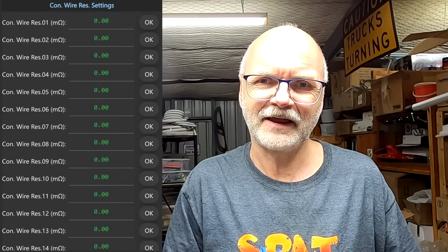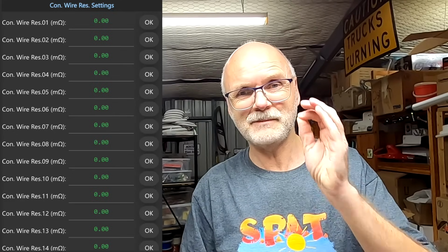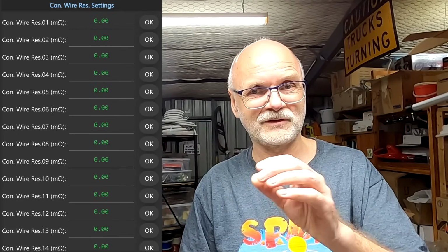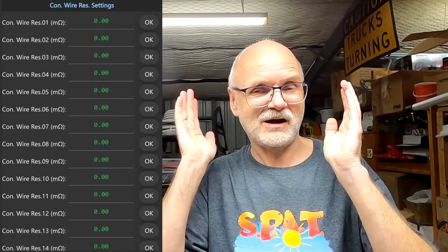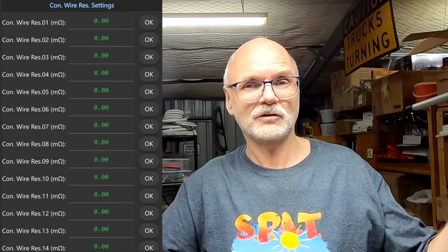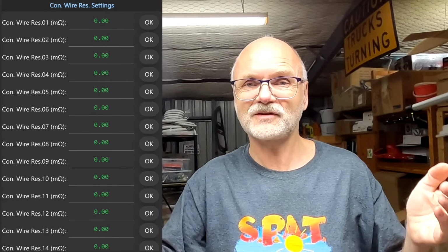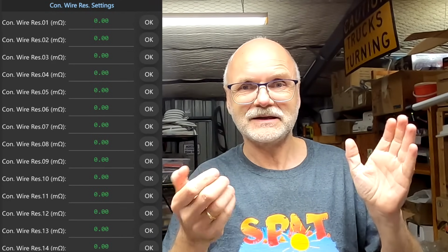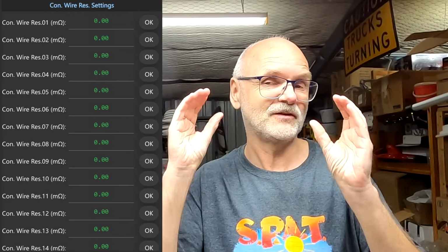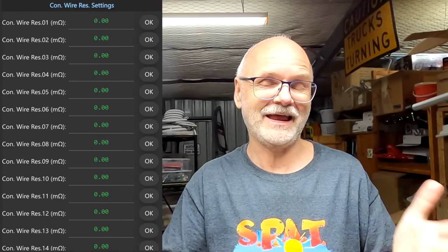Guys, I never paid attention to resistance in balance leads. Really not, because it is not important. The BMS only measures the voltage of your battery cells with these cables. And if they are only 200 millimeters long or 2.5 meters long, it doesn't make a difference when you measure voltage because there's no current flowing. And if the BMS balances this one cell, it doesn't measure the voltage at the same time. None of the BMSs do.